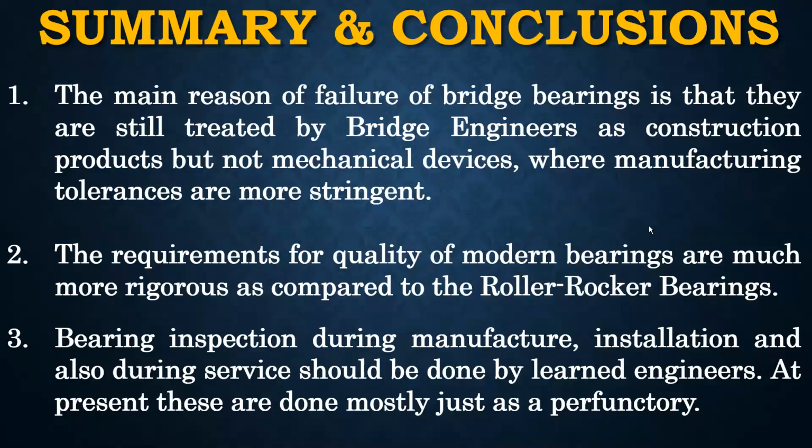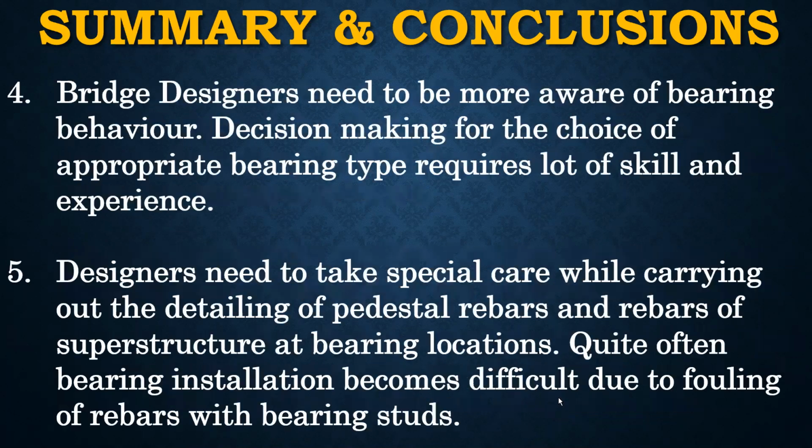So, I've come to the end of my presentation. To summarize, I would say that the main reason of failure of bridge bearings is that they are still treated by bridge engineers as construction products, but not mechanical devices, where manufacturing tolerances are more stringent. The requirements for quality of modern bearings are much more rigorous as compared to the roller rocker bearings. Bearing inspection during manufacture, installation, and also during service should be done by learned engineers. At present, these are done mostly just as a perfunctory.